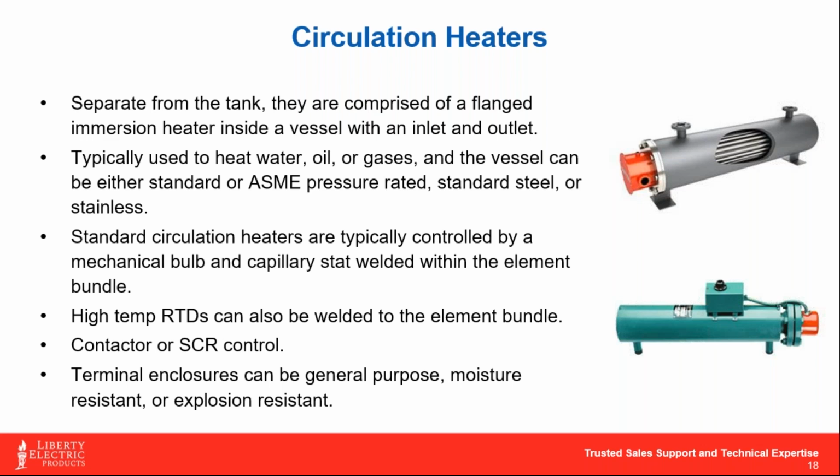And to control these, we can use pretty much any means. I mean, the most common are your contactor relay panels and SCR controls. I really like the SCR controls with these because when we regulate the voltage or current going to the heater, we can very much precisely dial in that heat to literally within tenths of a degree. So your control with an SCR is excellent. And it also soft starts the heater to help add more longevity to it.